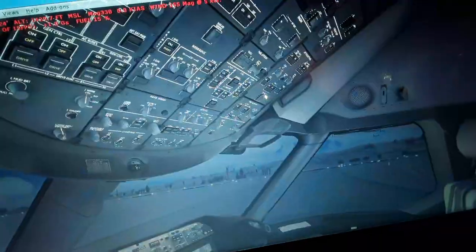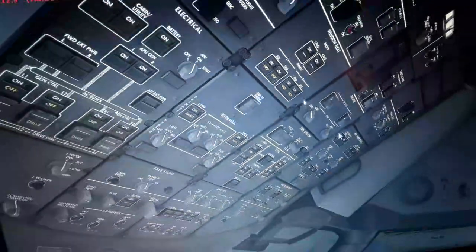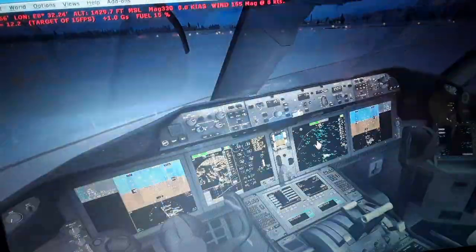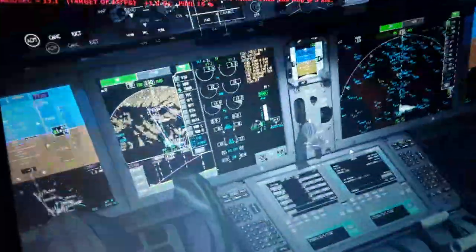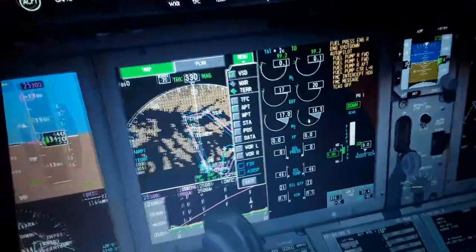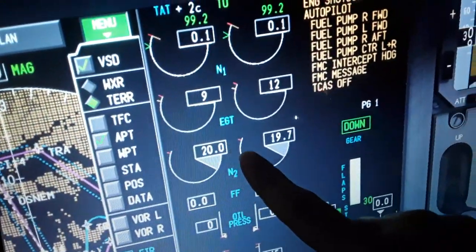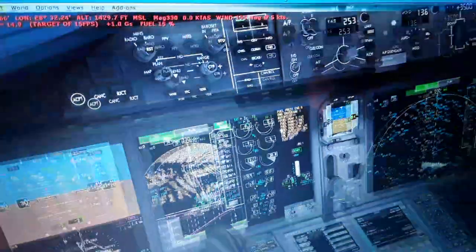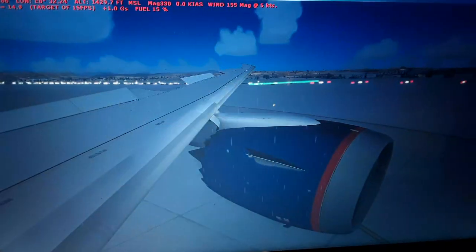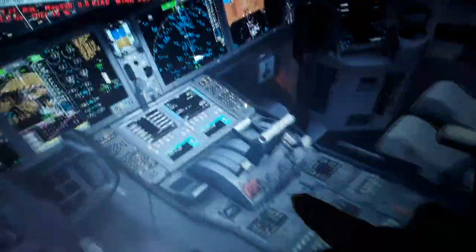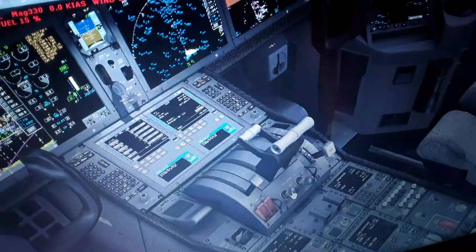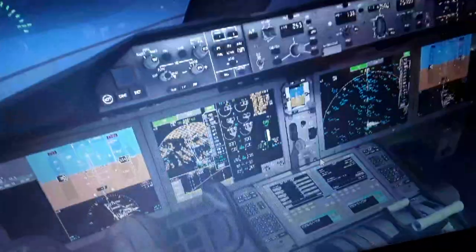So we go over here, turn on the auto start system. You will see the reconfiguration, yellow amber lights. So we have only pressurization right now from the APU to start the engines here. You can see the N2 is increasing. We have no fuel flow right now, so at 20% we have enough pressurization. We can turn on the fuel control here, left and right, both of them.